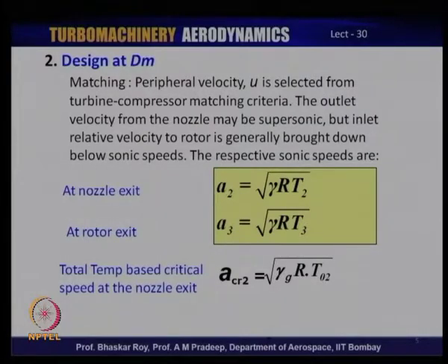Whether that value of U mean is sufficient for you to accomplish the amount of work to be done on the basis of Euler's formula of work done needs to be decided very quickly. Otherwise, the value of rotating speed RPM would have to be reselected or changed. Alternatively, the annular space definition of the particular turbine blade may have to be redesigned.